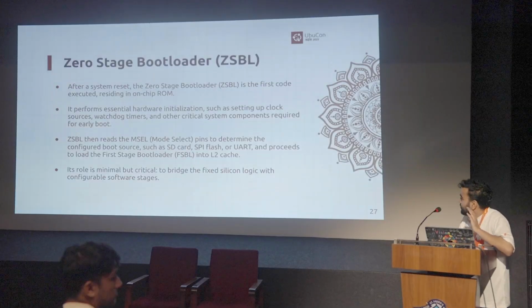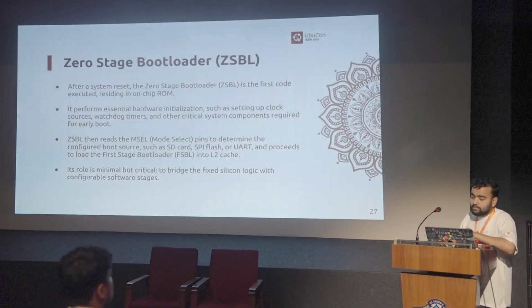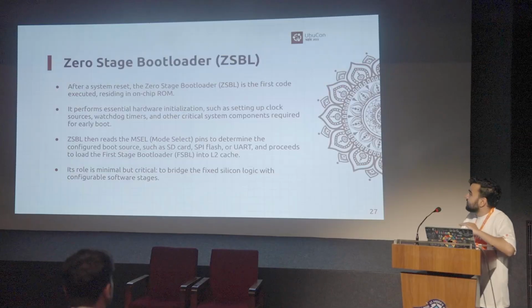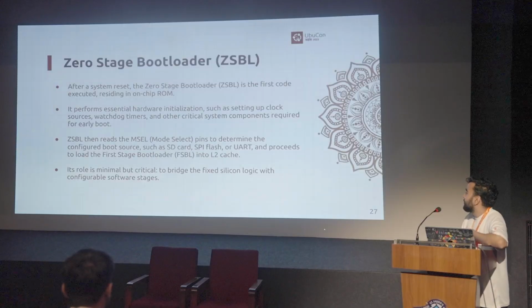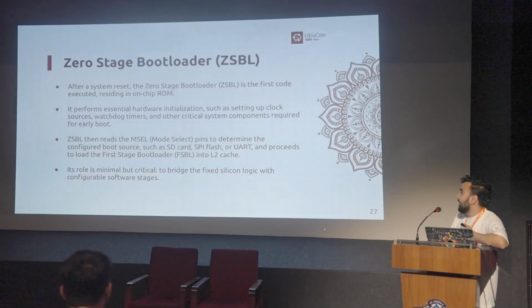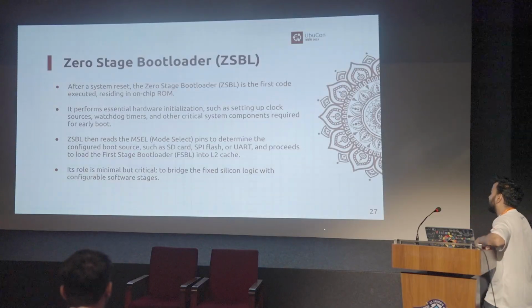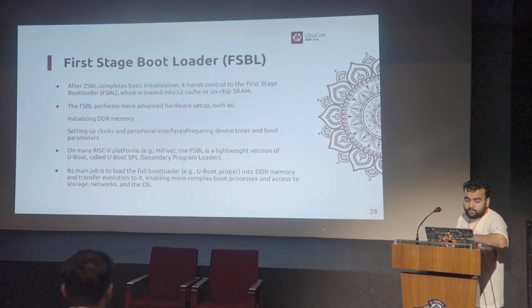Let's go through the stages we have discussed. After the system reset, it's the first code that runs. It reads the mode select pins to determine the boot source such as SD card, SPI flash, UART, and proceeds. Its role is minimal but critical. Let's go to the second one.